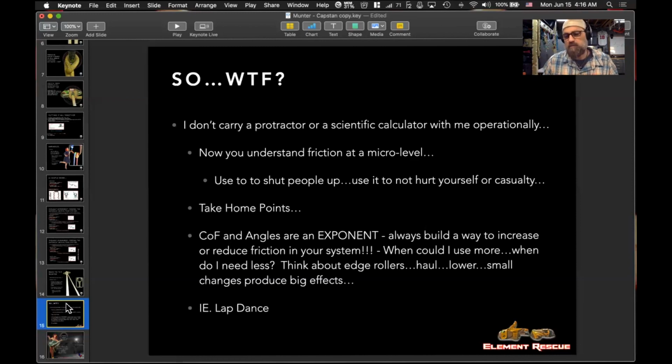At the same time, don't get crazy that I have to have these high efficiency bearings on the edges to be able to run my haul system up, to bring that theoretical mechanical advantage closer to the real actual mechanical advantage, because you can get away with just changing a coefficient of friction and having an exponential return in there.